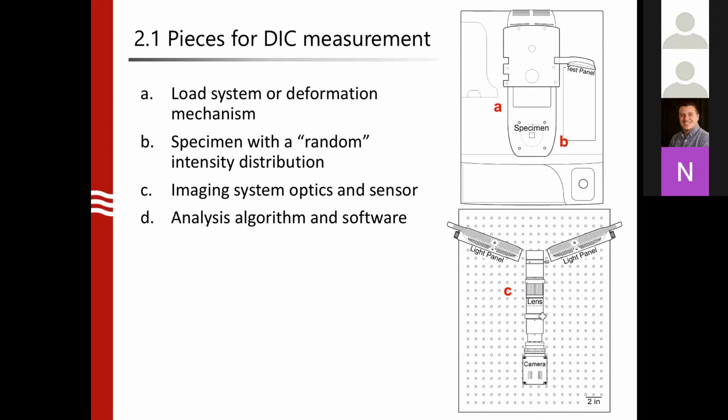So basically there are 4 parts you need to pay attention to. That's the loading system, which will give you the deformation, and the patterns: how do you paint the speckle pattern on the top of the surface, and how do you image them, and how do you do the post-processing to solve those deformations. So for the loading part,